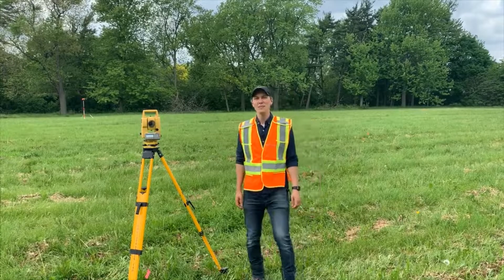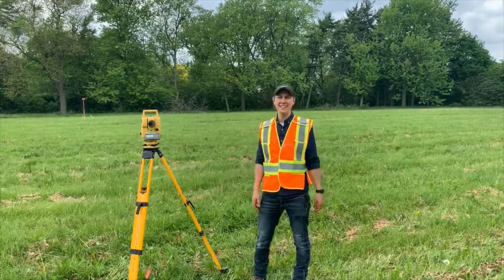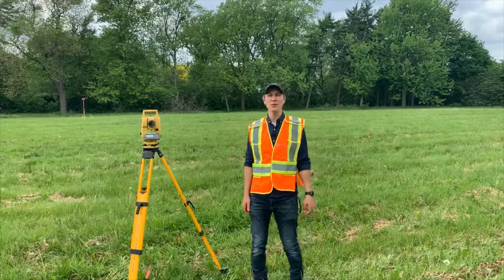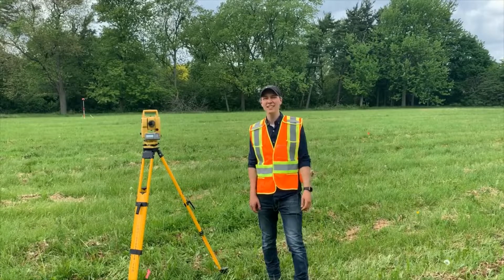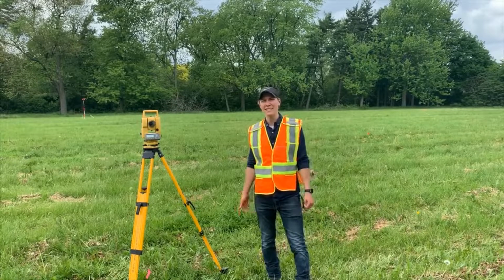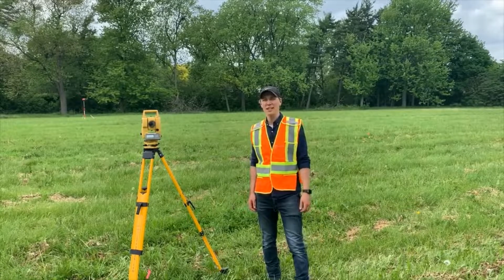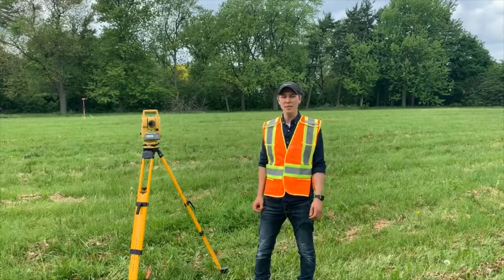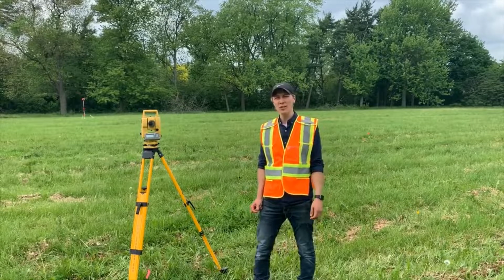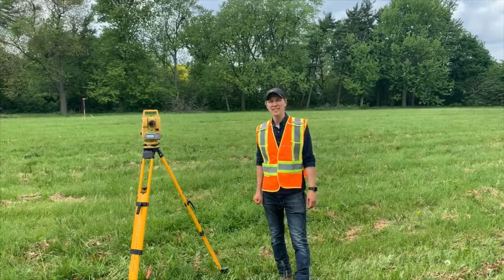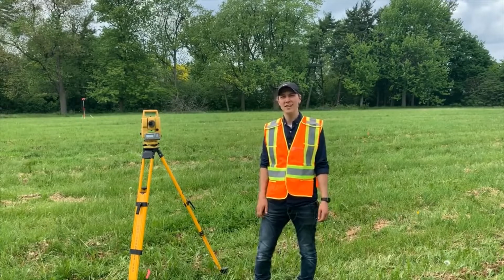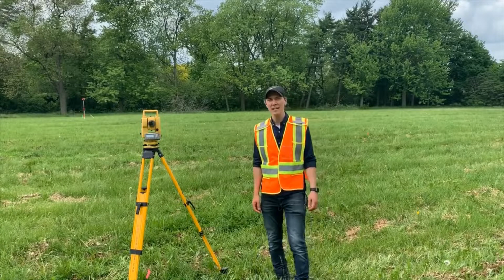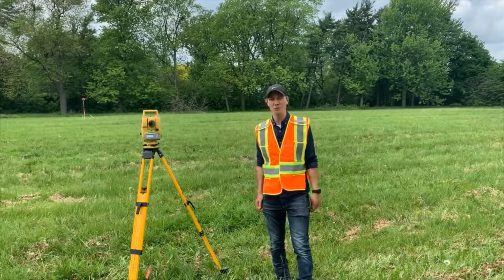We've set up our total station on station D6. You can record in your notes that we're doing traverse number 6, and you can also record the northing easting coordinates for D6 where we've set up our total station. It's important to note for this lab that we're only working with our horizontal. So we're working with our horizontal distance and horizontal rotation, and we're not looking at the vertical distance when we take each of our measurements, and that's because we're working on a horizontal plane.